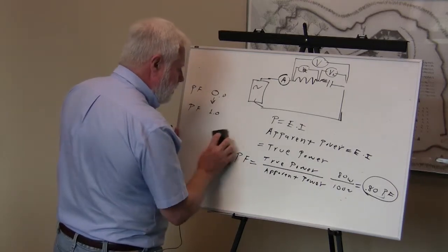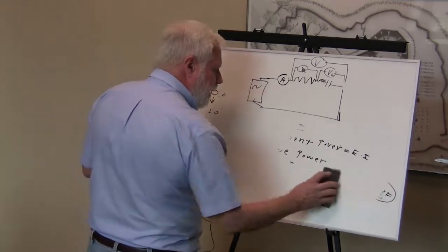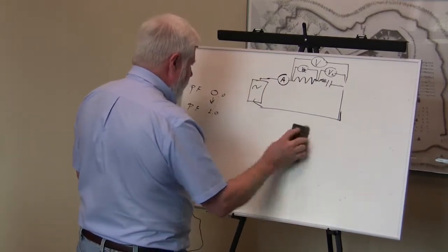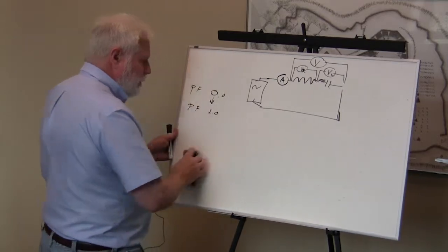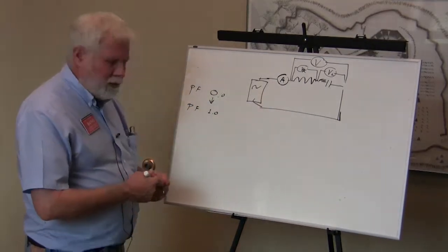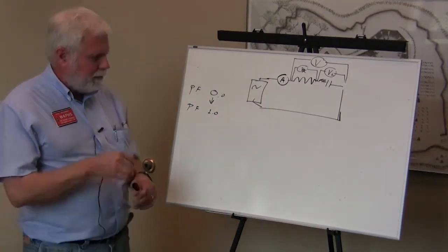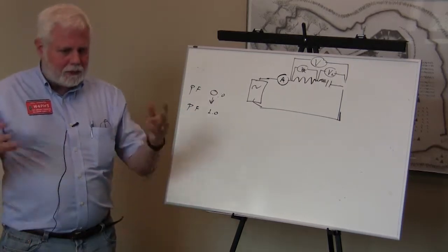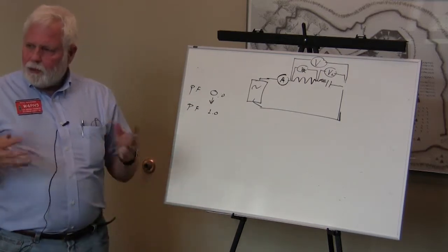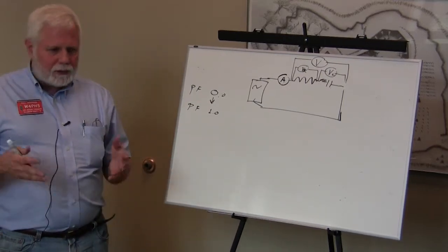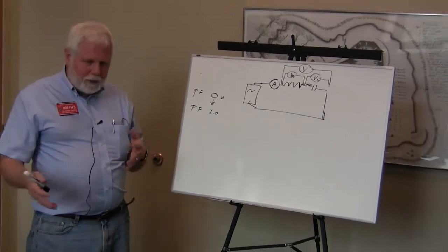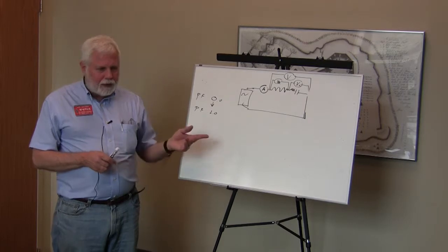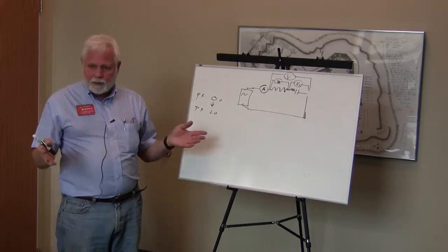Okay, now, let's talk about how we calculate power factor with phase shift and so forth. By the way, let me just as an aside here, let's talk about practical stuff. In your home, when you have machines, like an air conditioner compressor, a motor, those things always have power factors less than 1. The amount depends on how well they design the machine. A typical number might be 0.8, 0.75, somewhere in that ballpark.